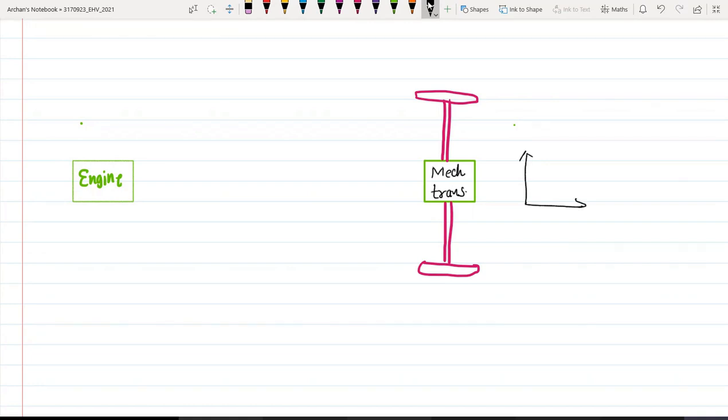I should have this kind of shape. So this is my tractive effort versus vehicle speed. This is our desired speed torque characteristics. Tractive effort versus speed, and speed torque characteristics will be achieved by the motor.